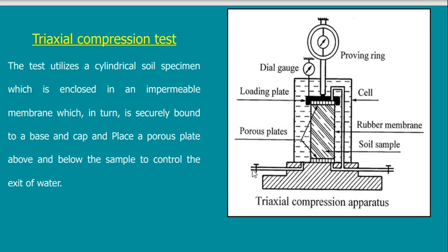It will push the sample all around. So when I use this tap and push water inside in high pressure, and then close this tap, it means that my sample is now compressed with water. It will stay like this. If I open this tap, then I will allow the sample to consolidate.